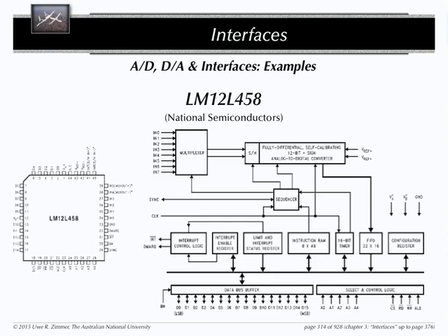Another frequently used one has a few more pins now. And one thing you see is there is one element of it, which is called the fully differential self-calibrating 12-bit AD. That's one module of this whole chip. And there's a lot of other things going on here. Most of them are concerned with how you communicate with this AD converter. You need to set parameters in this AD converter.